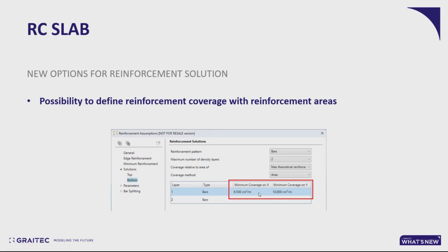So for example, for the bottom reinforcement in the X direction, the first layer that is covering the entire surface may have some specific value, and that can be the required one. But if we want to apply more reinforcement on some points, we can add additional bars that will be locally added automatically to the second layer. Okay, so now Advanced Design will check for these limits, and if we need more bars to be added, it will automatically add those to the second layer of rebars.